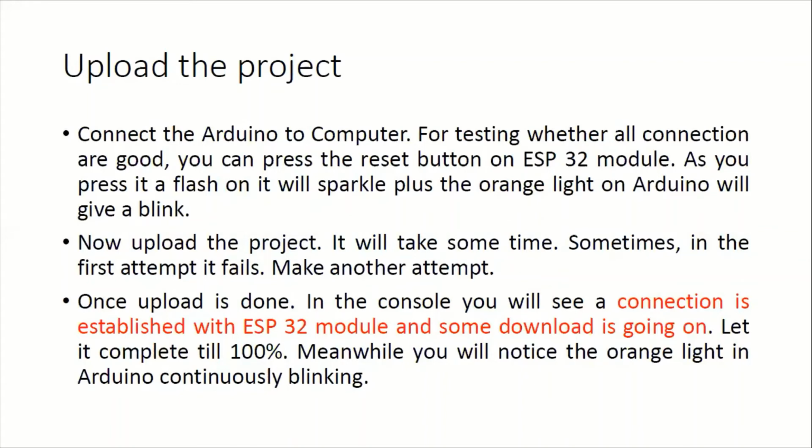It is basically trying to connect with the ESP32 module, and then it will download the code and all the relevant files to the ESP32 module. So let it complete till 100%, and you will also see continuous blinking of the orange light on the Arduino board.